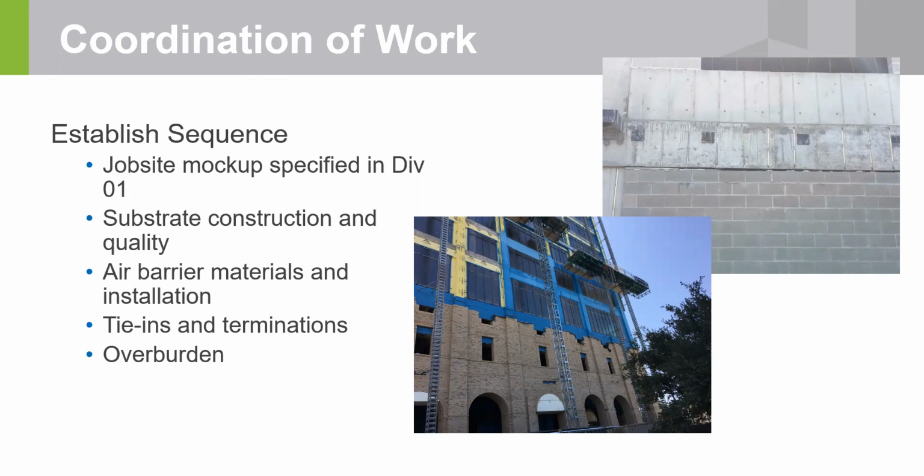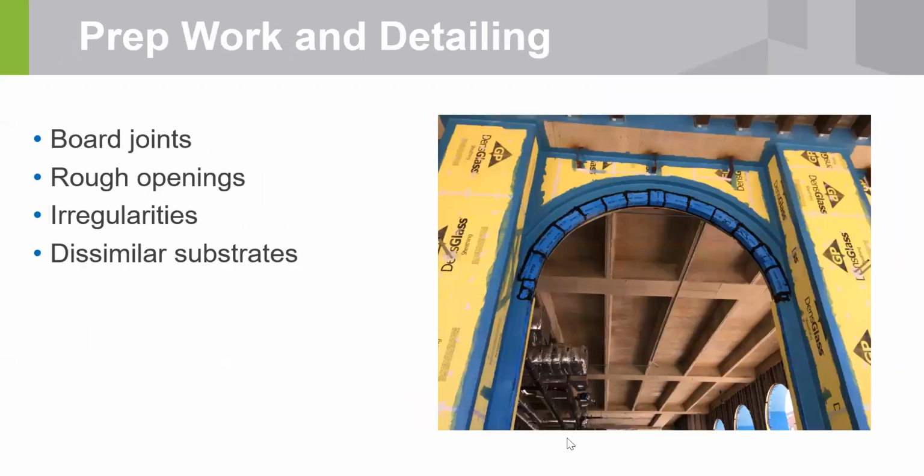Now the caulking trade has got to figure out how the heck to seal this window to the air barrier if this brick is up and in the way. So sequence of construction is very important. I mentioned that pencil test with the details, but you've also got to figure out what is going to be required to actually build that. Drawing it is the easy part.